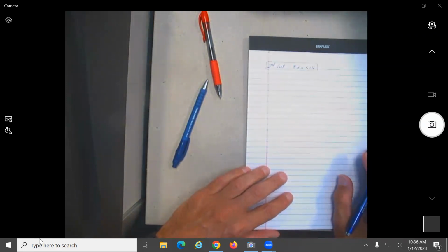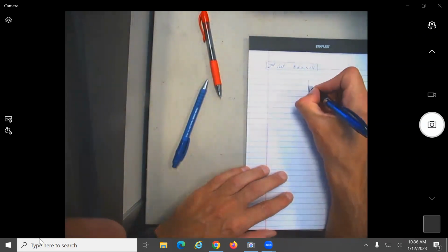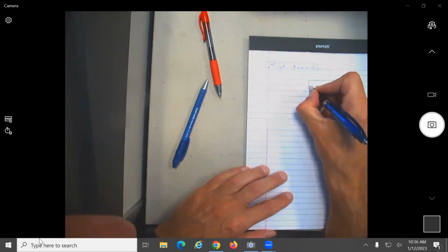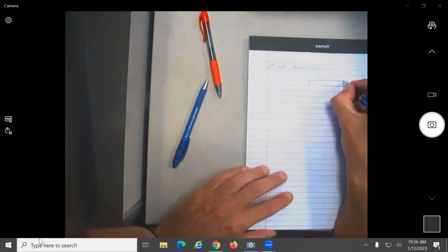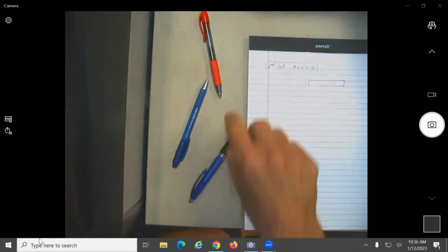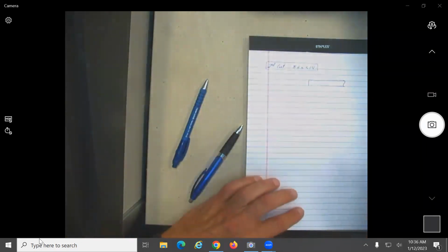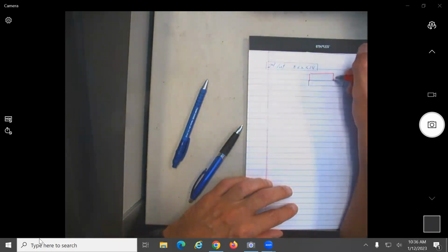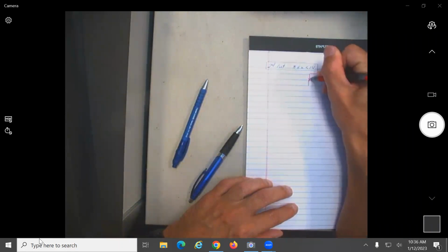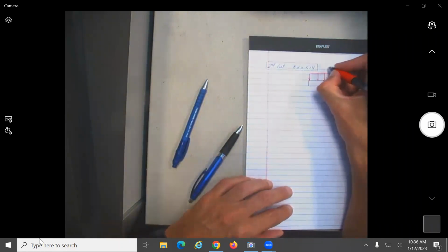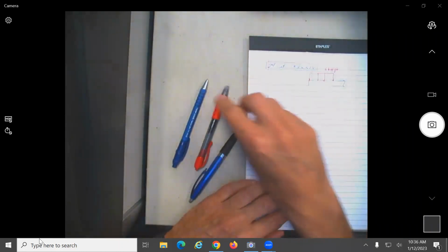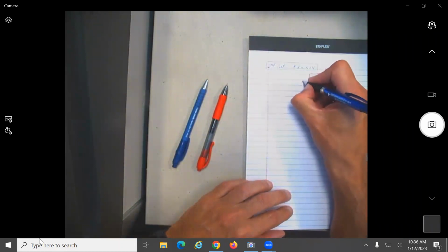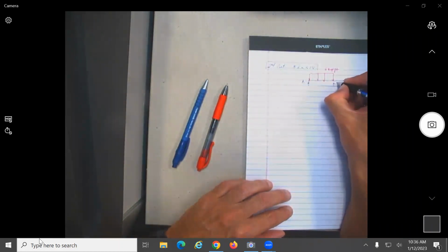Okay, so same as before, what is the first thing you need to do? Some type of free body diagram. So your free body diagram now, we are past the 8, so you can keep here the distributed load. How much was it? 6 kip. So this is point A, this will be point B.